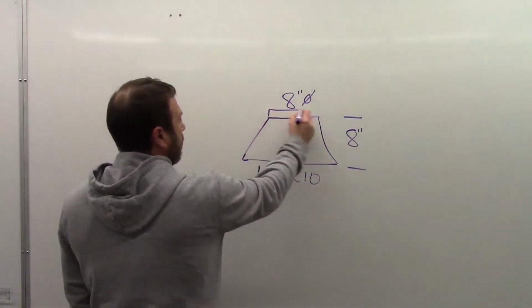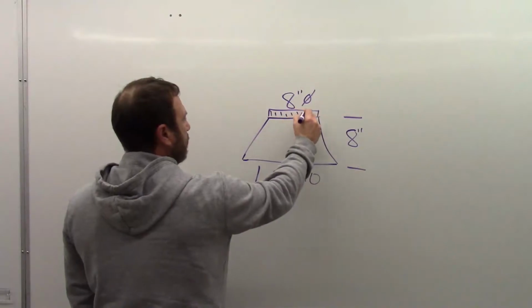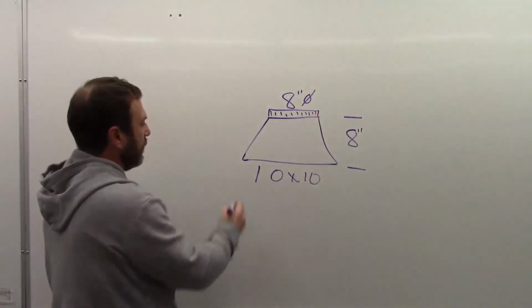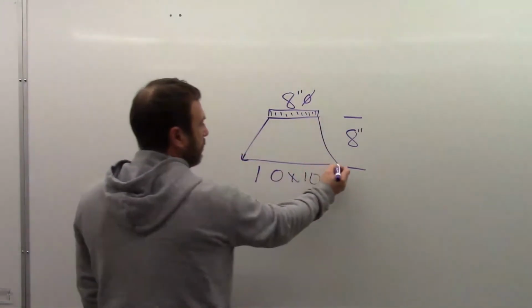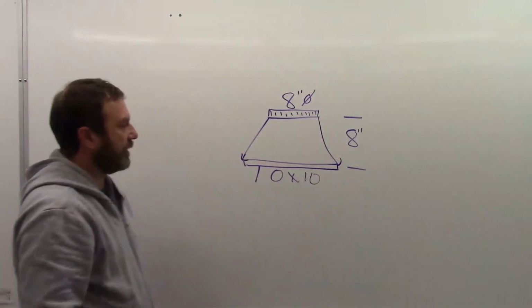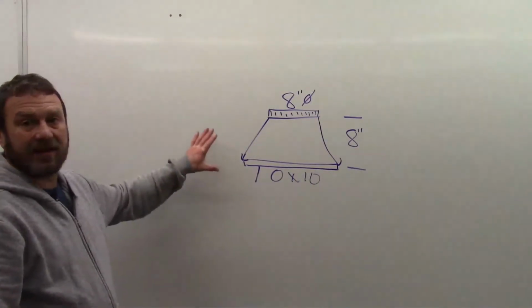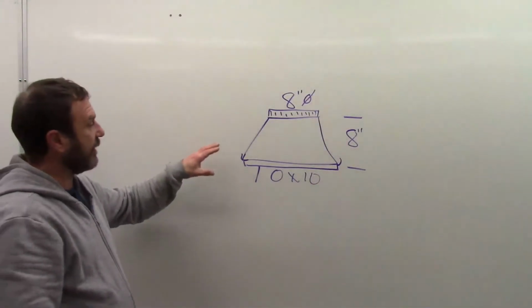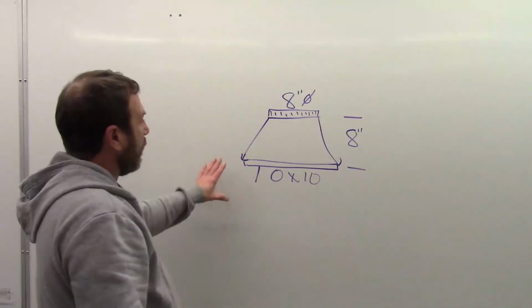We might have some other details on this. It might have a collar on it, might be a small end collar, so we'd crimp it and show the crimp there. Might be S and drive, so we could put some drive hooks in there, and our 1/2 inches straight. But that's a typical shop drawing, shop ticket that we would see for our project.